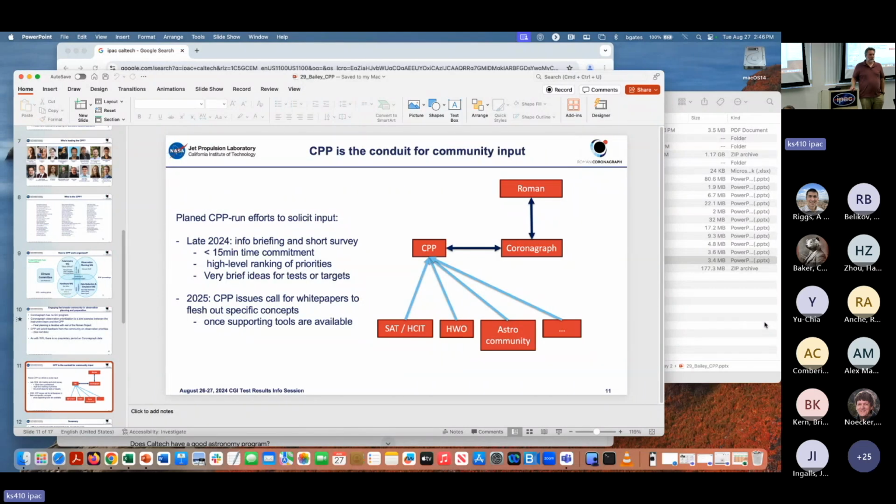I know something I'm super interested in is after you do your worst case slew, what the PID control time constants and the wavefront over time look like with the PID controllers, and how that compares against your models.